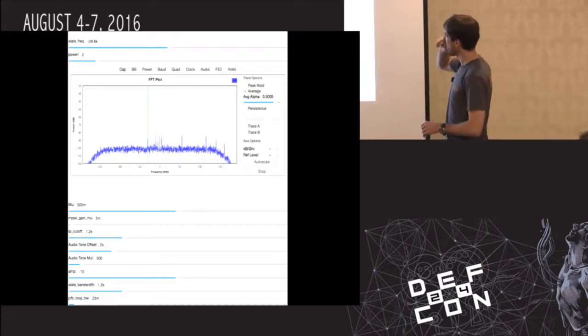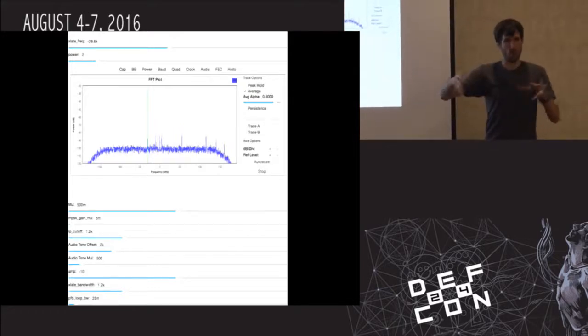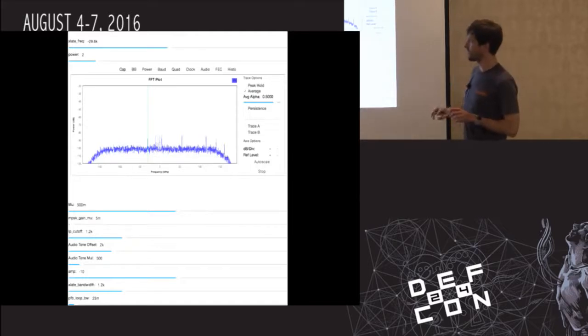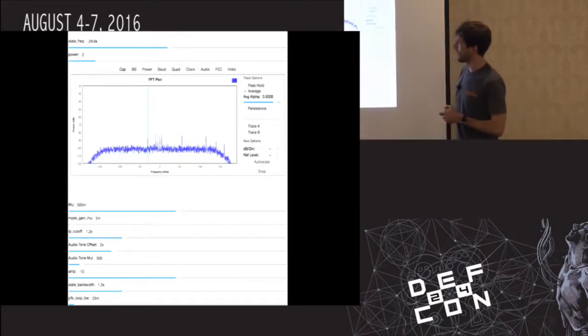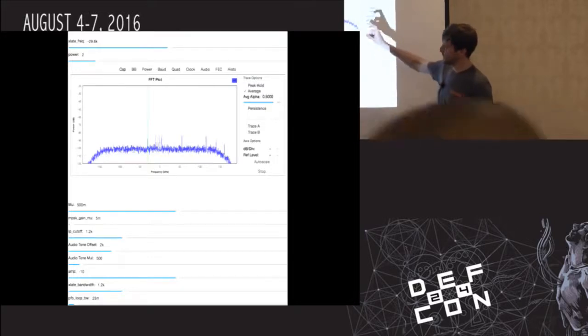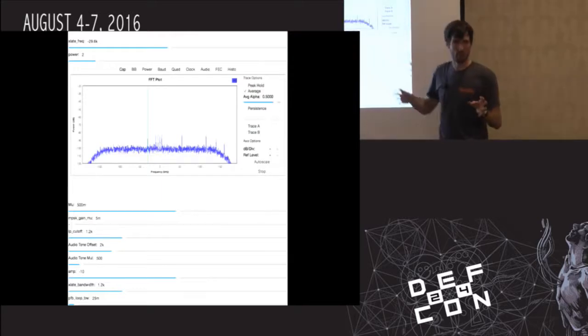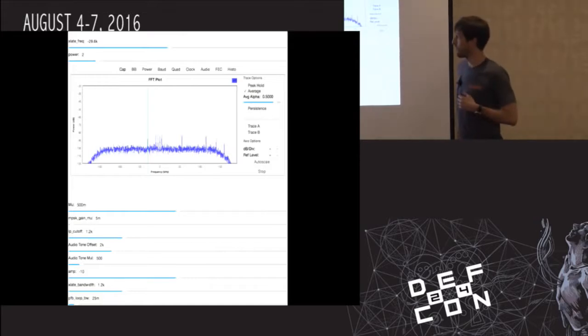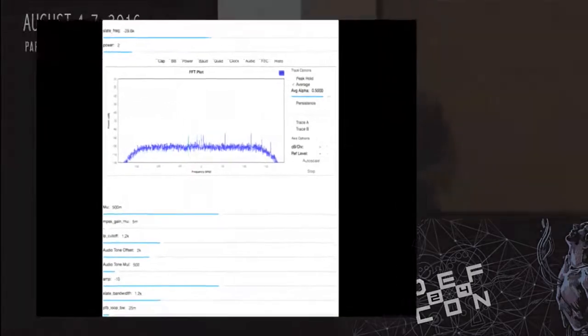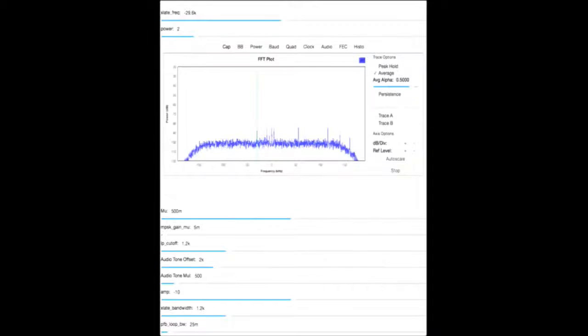So this is the old version. What we did initially was just record the spectrum for a while and then do offline processing. Remember, we only want to look at the P channel, and what you can see here is the P channels that are actually available coming down on the different, I think, spot beams. Because it's a satellite link, obviously your signal to noise ratio isn't fantastic, but luckily it's good enough that you can use the simple blocks, demodulator and clock synchronization in GNU Radio to do it. You don't need to do anything particularly fancy at this link budget anyway.